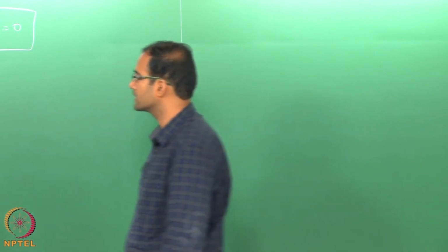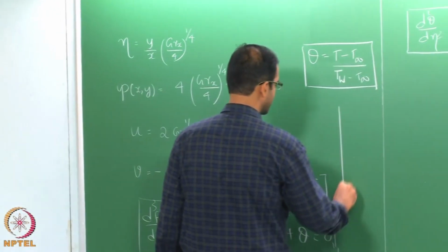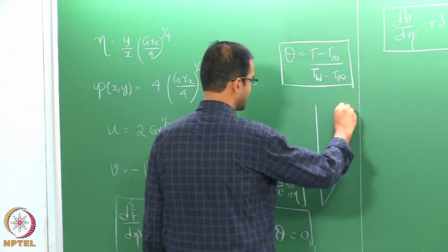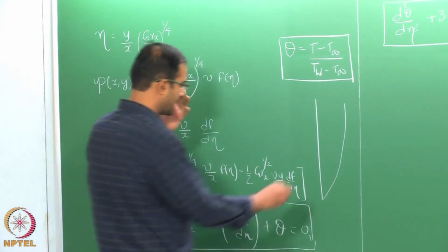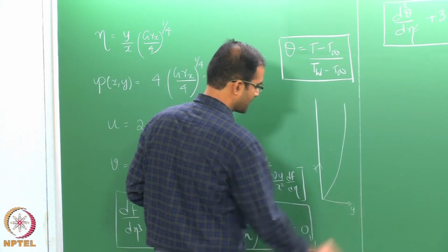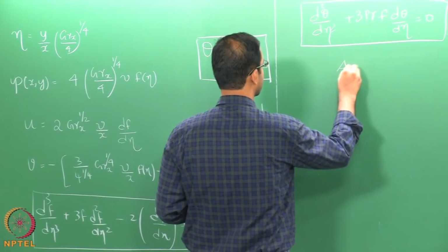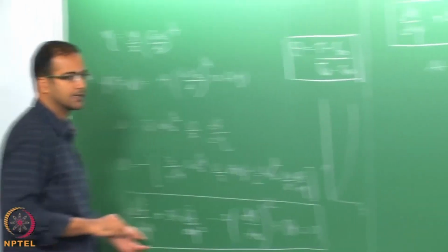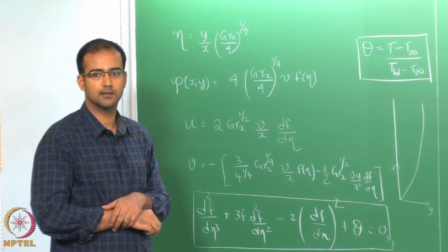So, what are the boundary conditions here? If you take the case of the vertical plate, pretty much similar conditions as in the case of external forced convection. We have the coordinates x and y. So, to solve this we need to define 3 conditions for f and 2 conditions for theta, right.